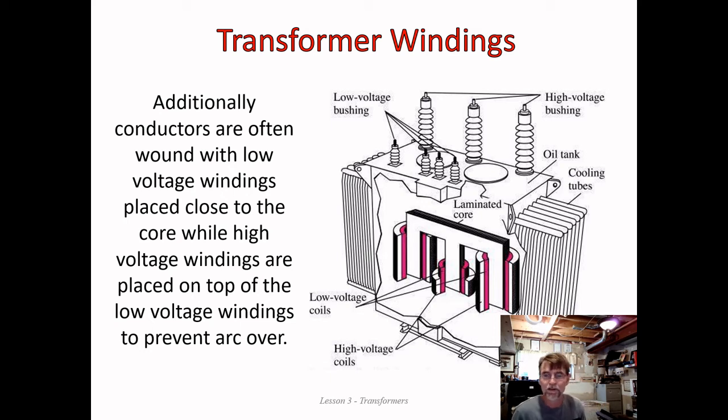So this is something I haven't talked about yet. Okay, but in order to change, this is coming in part 3, in order to change the voltage, these two coils must be different. Okay, if the two coils are identical, then we call this an isolation transformer, and it doesn't change the voltage and the current. It stays the very same. Okay, it's called a 1-to-1 transformer, and the voltage in is the voltage out. Okay, if the two coils are the same.